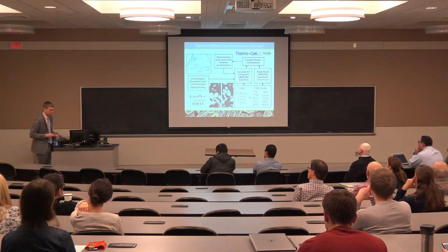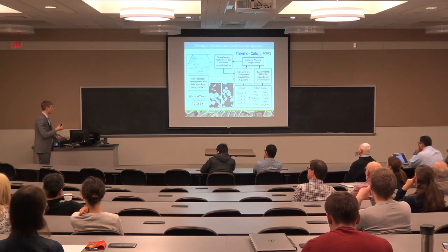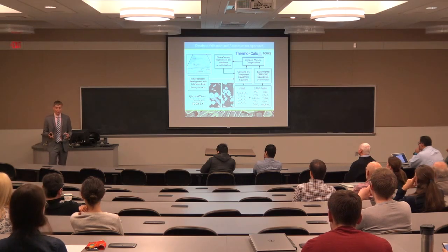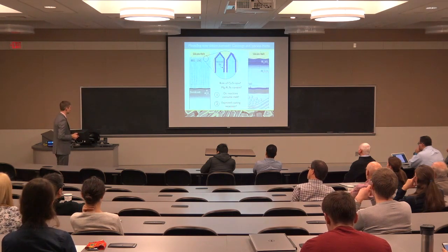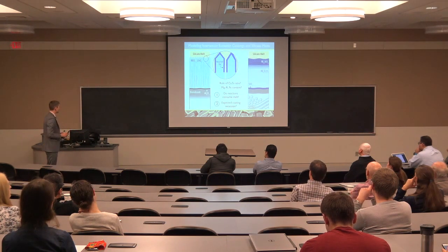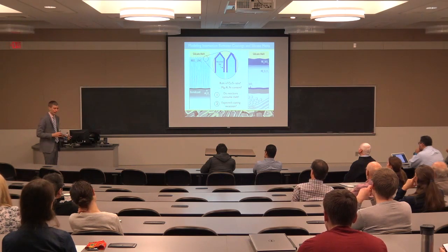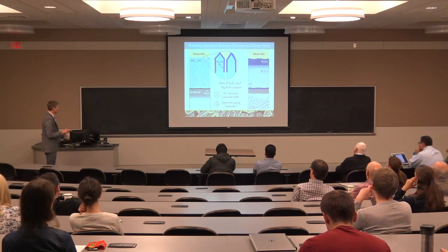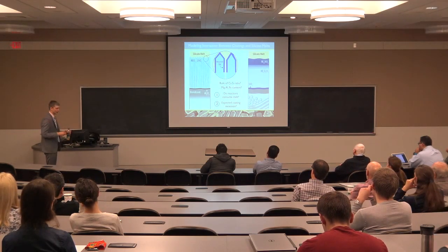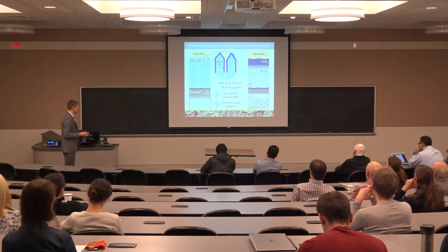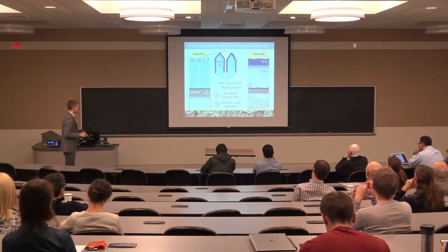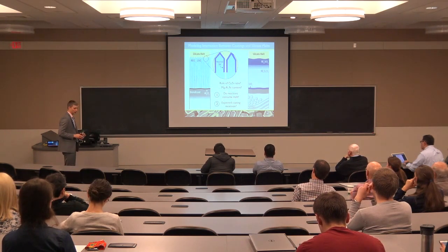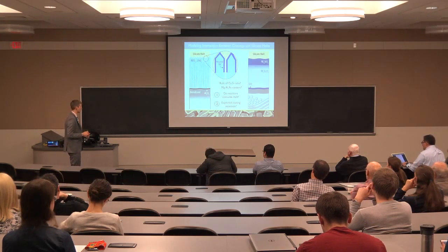And once we had a database that was working well and could reproduce a lot of experiment results, we can then move forward and actually apply this to understand, in a broader context, the behavior of different coating systems. So to finish today, I'll share 2 brief case studies of how we've done this. Our overall goal is to understand how the calcium-silicon ratio and changes in the amount of the other constituents, magnesium, aluminum, iron, in the deposit influence the reactions. We want to know, do the reactions still consume the melt? And how far might we expect the coating to recede or degrade before the reactions stop?